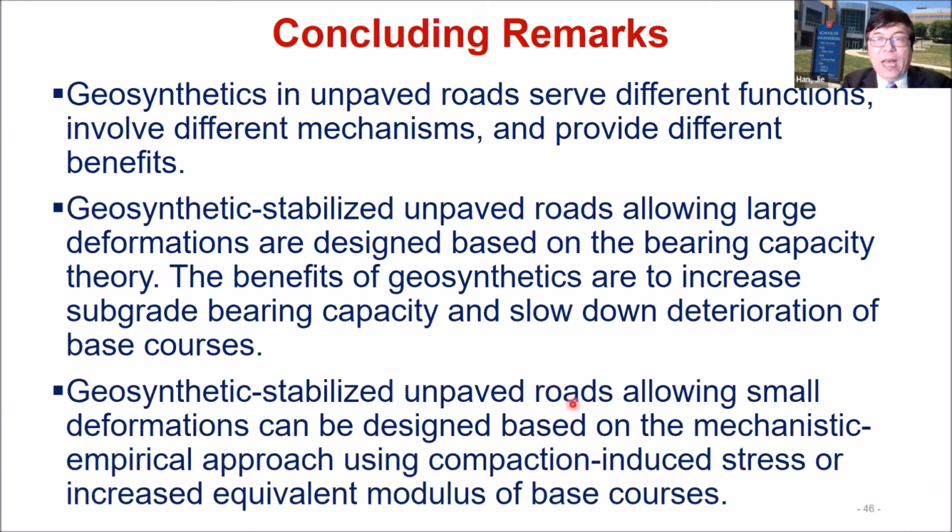But geosynthetic stabilized unpaved roads allowing smaller deformation can be designed based on the mechanistic-empirical approach, using compaction-induced stress, or increased equivalent modulus of base course. With that, I thank you very much.